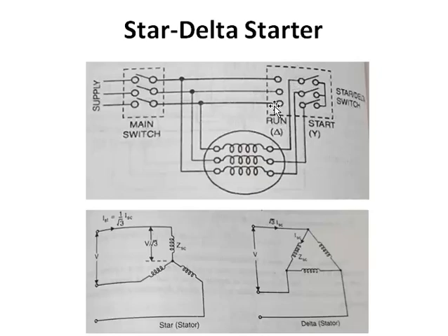These are 3 terminals, onto which one end of the winding is connected. At the end we have 3 more terminals, and those are short circuited, and we have 3 more terminals in the middle, and the other end of each winding is connected to those terminals.